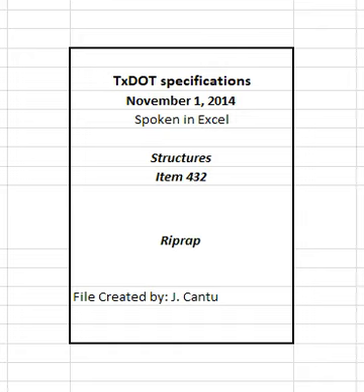Sprinkle and consolidate the subgrade before the concrete is placed as directed. All surfaces must be moist when concrete is placed. Compact and shape the concrete once it has been placed to conform to the dimensions shown on the plans. Finish the surface with a wood float after it has set sufficiently to avoid slumping to secure a smooth surface or broom finish as approved. Cure the riprap immediately after the finishing operation according to item 420, concrete substructures.